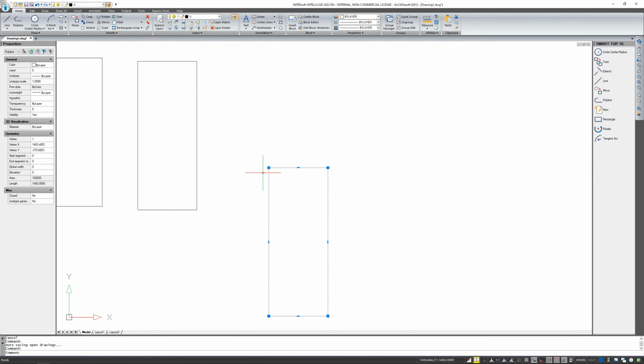You can assign the width of such a polyline, and you can also specify the width differently at different ends. For example, at one end it will be a value of 1, and at the other end a 5. It will simply be an arrow. Such elements are defined in this property window, here in these places.